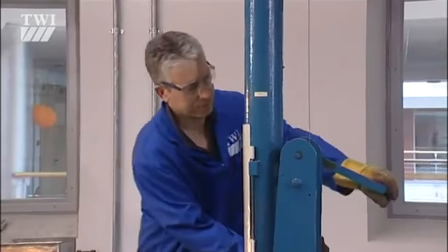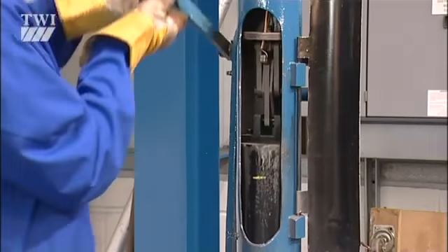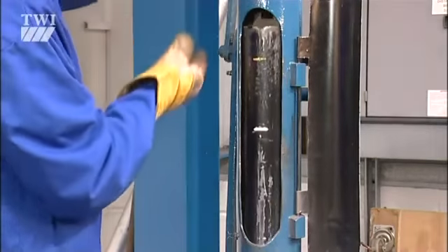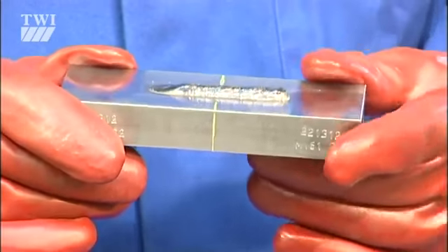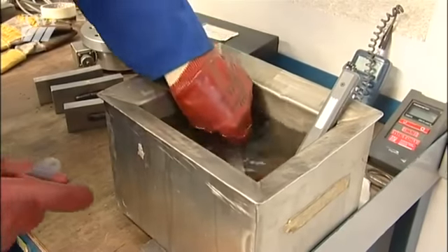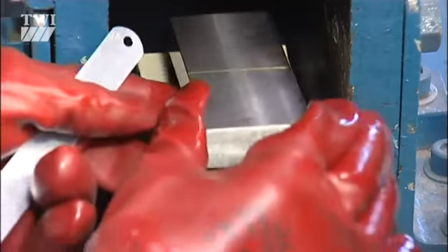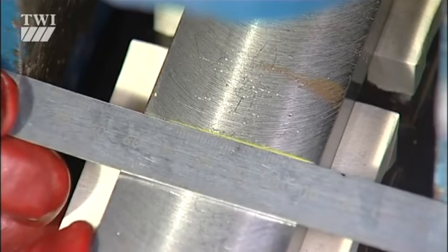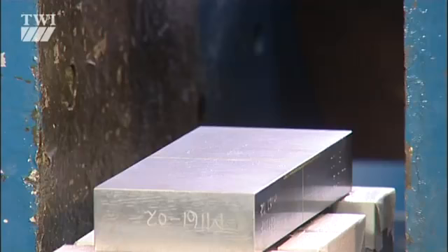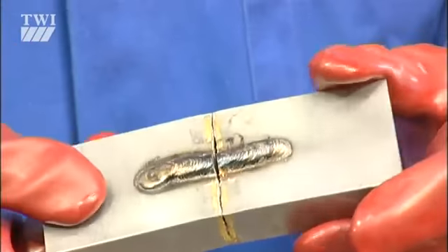There are, however, a number of qualitative tests which dictate a go or no-go result. Typical of these is the nil ductility temperature test. It's confusingly dubbed the NDT test. The sample size is standardized, depending upon plate thickness. A brittle crack is introduced on one side, and the simply supported specimen is struck in a standard way. The test is carried out on a number of specimens at progressively lower temperatures until the test piece breaks in a brittle fashion. This is known as the nil ductility temperature, or NDT.